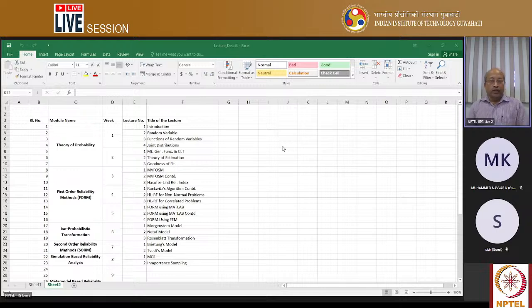Now, in these two scenarios, where we cannot write the limit state in explicit form, or even in the explicit form case, if we get some results from either the first order method or second order method, how can we verify these results? For that, we have simulation-based reliability analysis. There we discussed Monte Carlo simulations and variance reduction techniques. Monte Carlo simulation particularly is a very versatile technique. In fact, you can simulate any uncertain environment using this. Of course, nothing comes free.